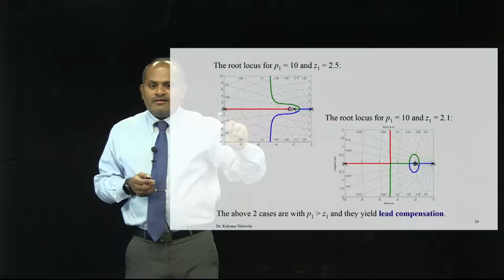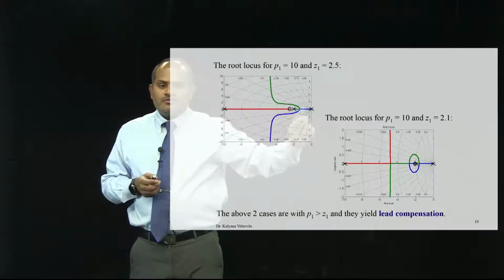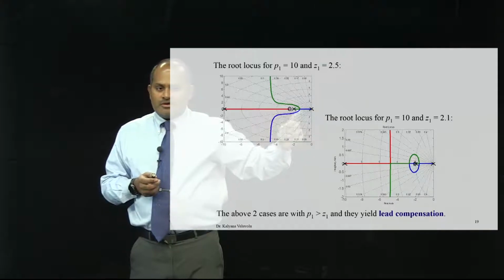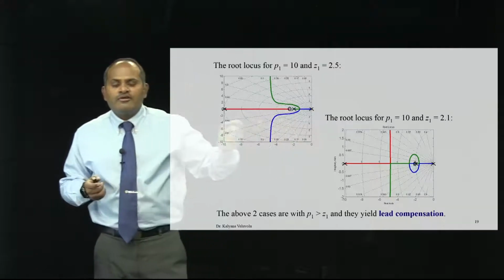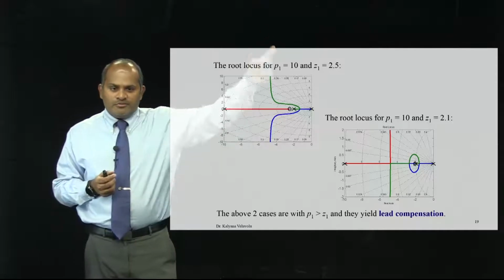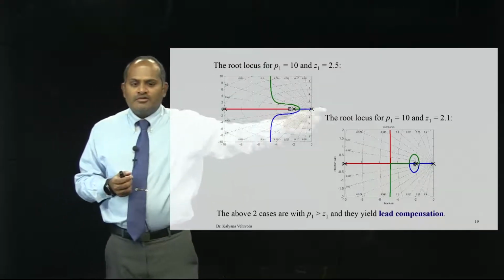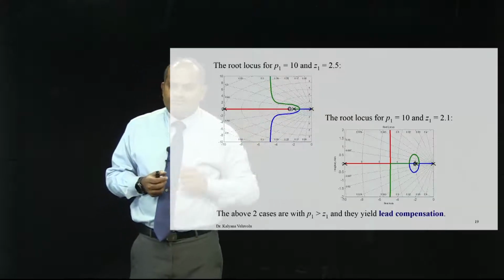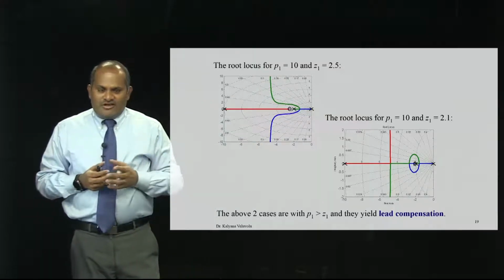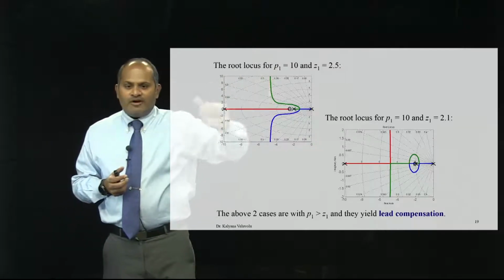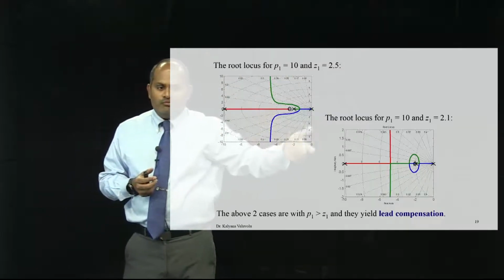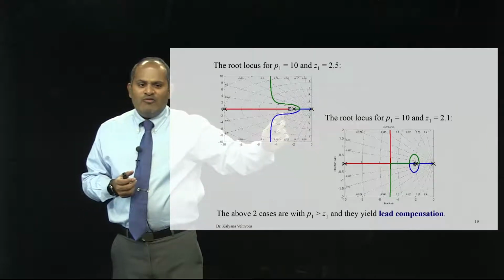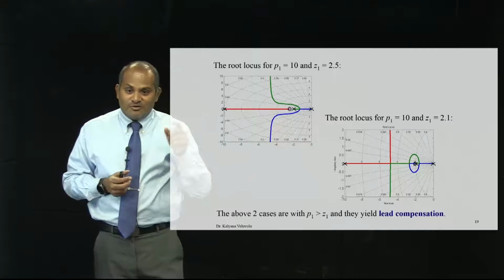But still, because of the root locus structure, these 2 poles break away. The asymptotes are here because the centroid will be here. Because the difference between poles and zeros is 2, you have 2 asymptotes, at 90 and minus 90. So these 2 poles break away and go here, and this pole goes to 0. This is for the scenario when the pole is far away, 0 is closer. If we reverse, or if I place this pole very close to this 0, that's going to be interesting.